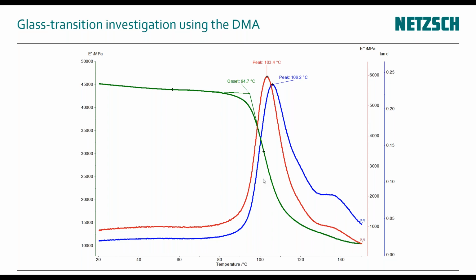They are just holding, in our case, the carbon fibers together, but they gain so much more mobility that the composite part loses its structural integrity crossing the glass transition temperature, and the effect is physically just higher than the increase in the specific heat capacity that we get from the DSC. So some people say the DSC is a more indirect method to detect the glass transition temperature, and the DMA is really a direct method to display the mechanical properties as they change along the glass transition temperature.